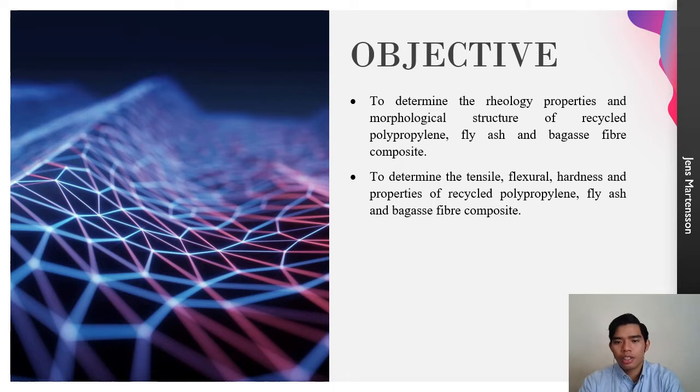The objective of this project is to determine the rheology properties and morphological structure of recycled polypropylene, fly ash, and bagasse fiber composite. To determine the tensile, flexural, and hardness properties of recycled polypropylene, fly ash, and bagasse fiber composite.